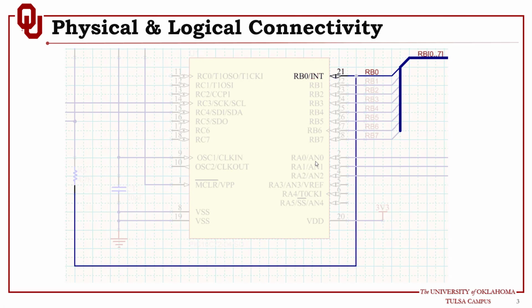On the other hand, net labels reduce the amount of wiring, but instead the reader must scan the sheet to find all potential connections. As a designer, you are free to decide which connectivity model best suits your design, including a mixture of both techniques.